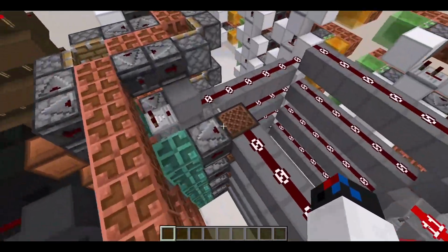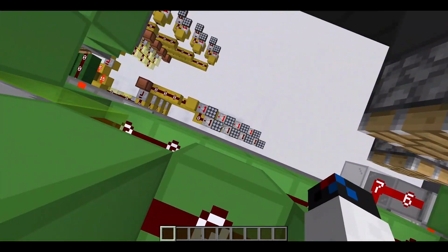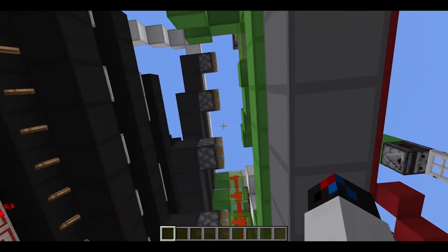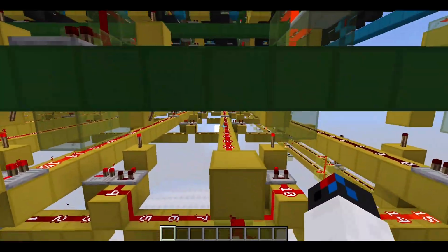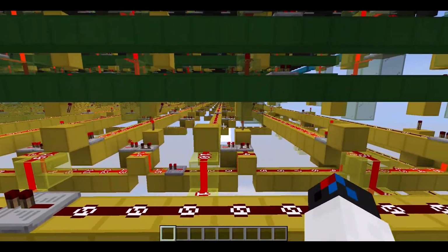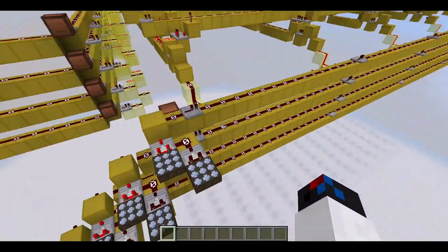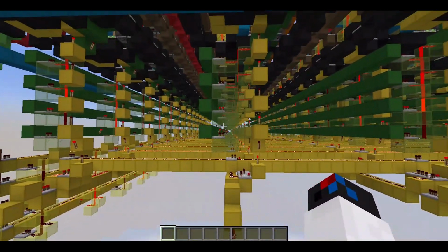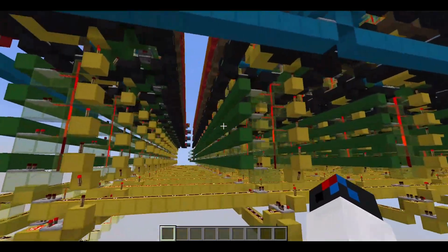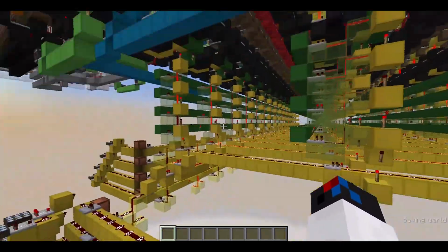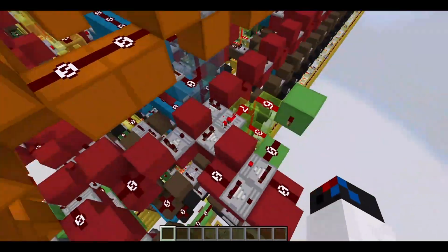So we take the signal from the head here, and then we input the symbol to this decoder right here to find the exact column that the cell is on. And then here we feed the state in to find the exact row of that cell, and we find the cross section between the symbol and the state to find the exact cell that we want. And then the output of that cell will go to the output here.